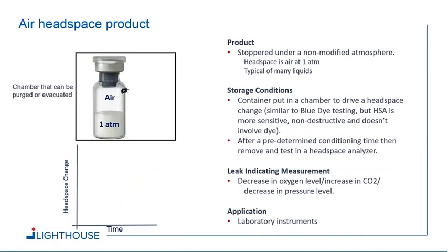So now the idea is you want to drive a headspace change, and it's actually a very similar approach to blue dye testing, where you put containers inside a bucket with dye, you seal it and you overpressure it, and you try and drive those dye molecules through a defect into the container.